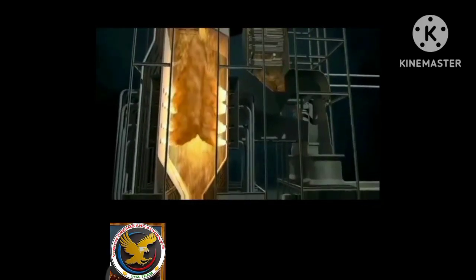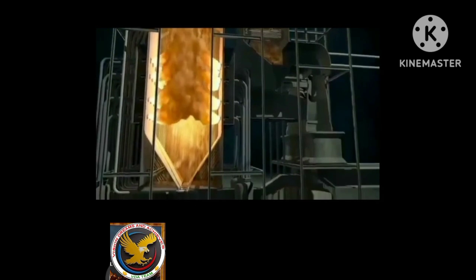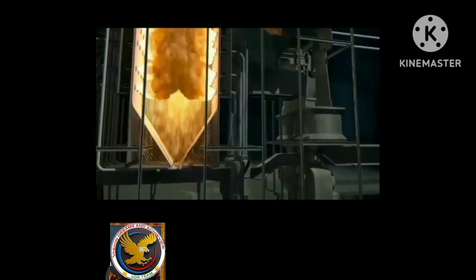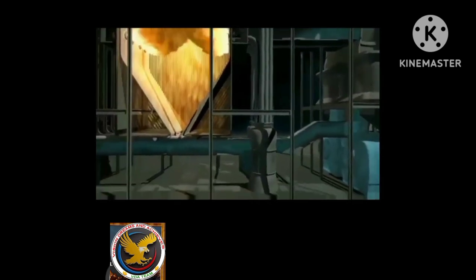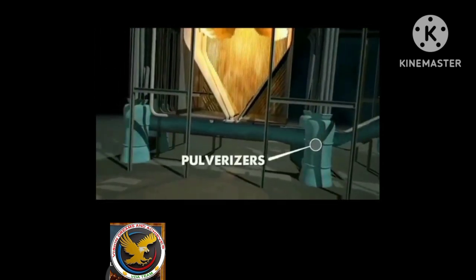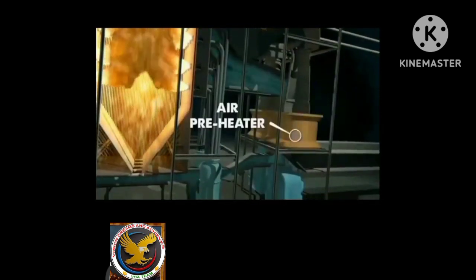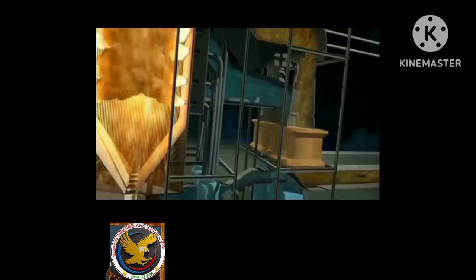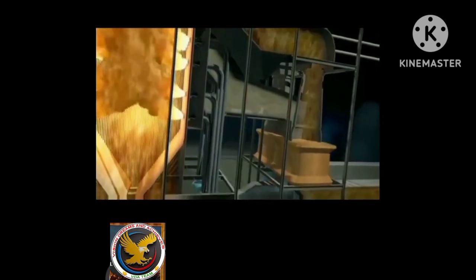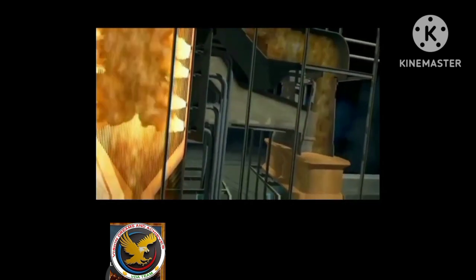as they have been since their origin, involve the complex production and manipulation of steam. The forced draft fan blows air into the system. A portion is routed to the pulverizers, which crush coal into a fine dust before pushing the mixture up through feeder tubes. The other portion passes through an air preheater, which transfers heat from the exhaust gases to the incoming air, raising the air temperature, reducing moisture, and producing a cleaner burn.